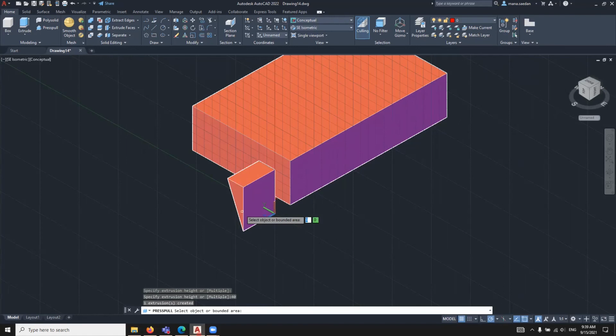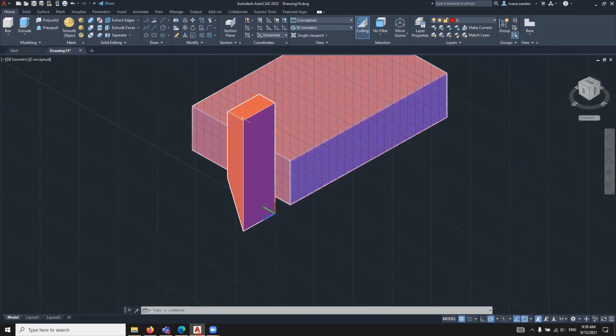Okay, we come back to the one that I said. If we create this and we move in and then we try to subtract it, very difficult. So the cheated way is that I will create this object larger but remain this area the same. I just press pull. It depends on which way you prefer. It depends on the situation. I press pull something on top here and extend it upward. The dimension we don't care. We just make it bigger so it's easier to subtract later on.